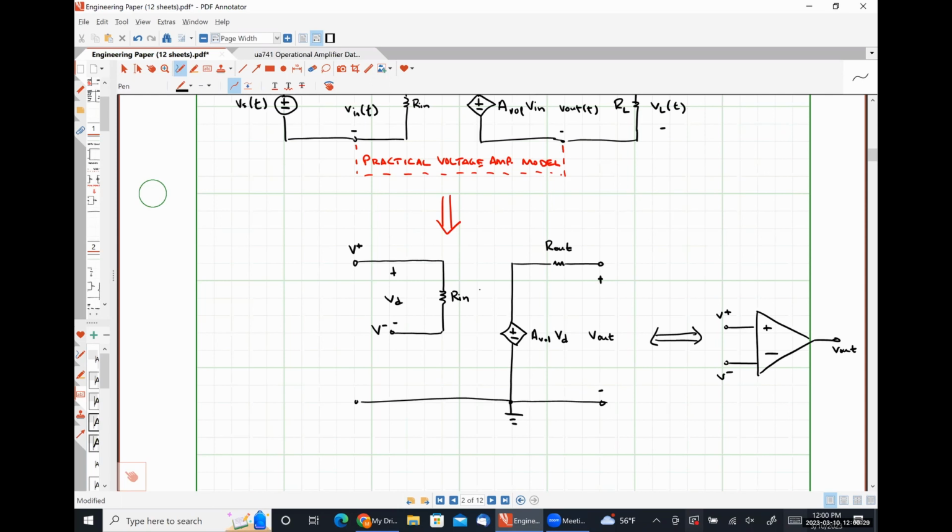Yes. Other than a signal flatlining, are there any bad things about saturation? No. I mean, I say no, but if you were to put some huge voltage at the input, you could burn out the op amp because you could have dielectric breakdown that would literally fry the internal circuitry. But from a performance perspective, there's nothing bad about saturating at the supply rails. It's just what the physical limitation of the system is.